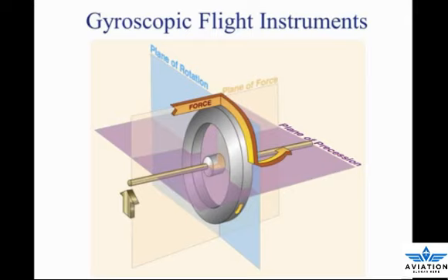change in direction. Using the example of the bicycle, precession acts on the wheels in order to allow the bicycle to turn. While riding at normal speed, it is not necessary to turn the handlebars in the direction of the desired turn. A rider simply leans in the direction that he or she wishes to go. Since the wheels are rotating in a clockwise direction when viewed from the right side of the bicycle, if a rider leans to the left, a force is applied to the top of the wheel to the left. The force actually acts 90 degrees in the direction of rotation, which has the effect of applying a force to the front of the tire, causing the bicycle to move to the left.